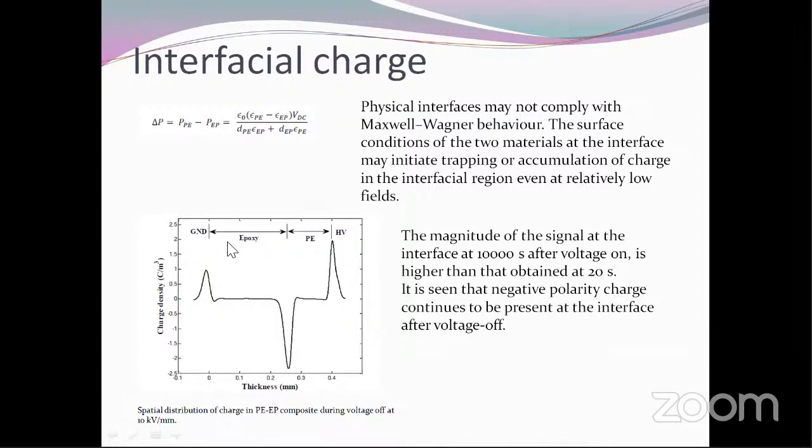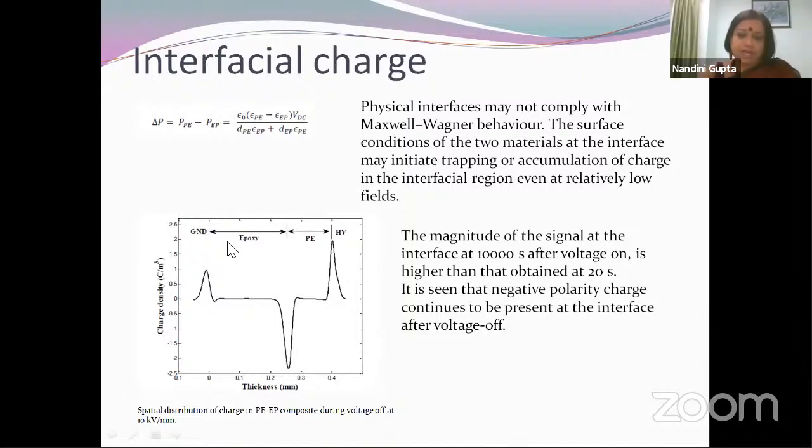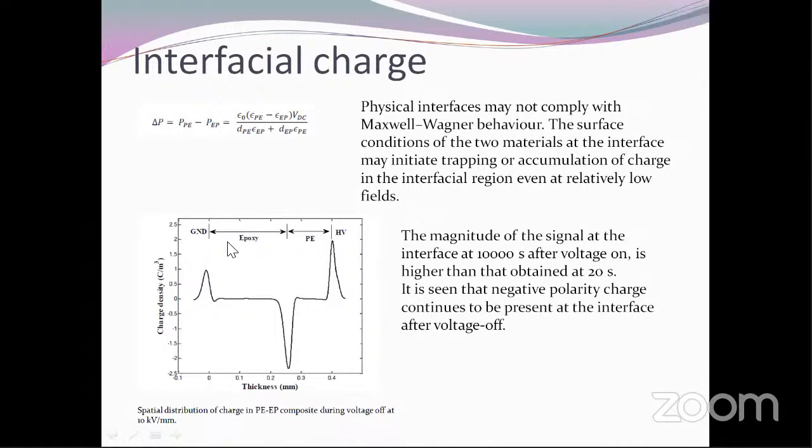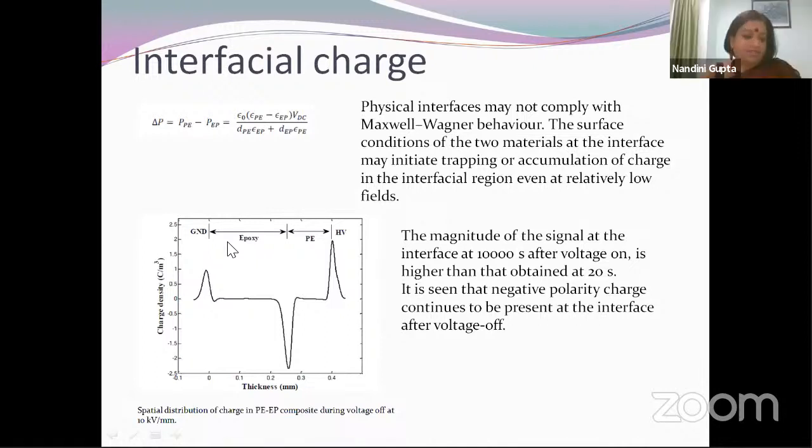Can we refer to the charge accumulated below the threshold level of the material as surface charge? I think I somewhat answered this question as well. No, surface charge is charge. I'll just put it this way. You have a surface. Let's say I have a corona here. The charge is here. It's free charge. And it's sitting there because it's nowhere to go. The dielectric does not allow conduction. So the space charge sits there. It's free charge, which is physically resident on the physical surface of the material.